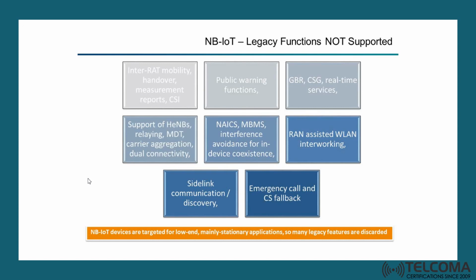Fancy interference cancellation techniques such as NAICS, that is network assisted interference cancellation and suppression schemes, MBMS, interference avoidance for in-device coexistence, etc. Anything fancy is not supported. Even RAN assisted WLAN interworking is not supported. Anything like sidelink communication, discovery, etc. is not supported.